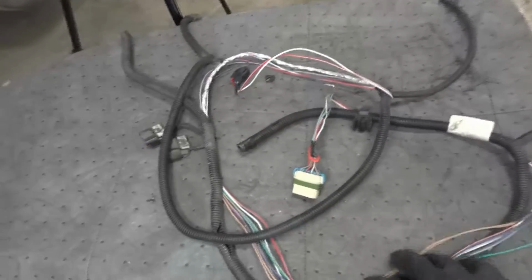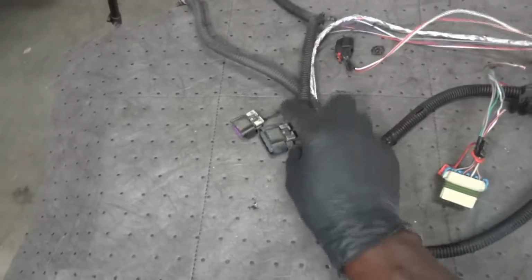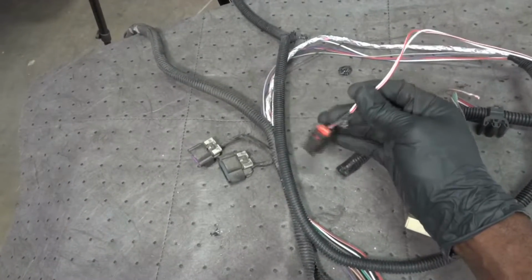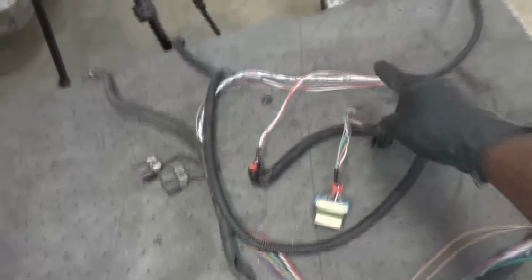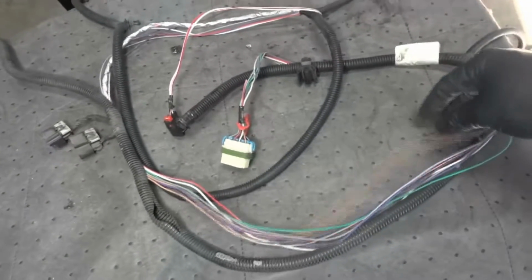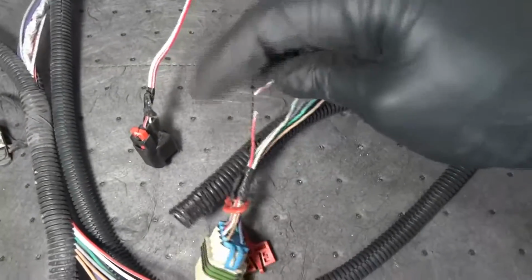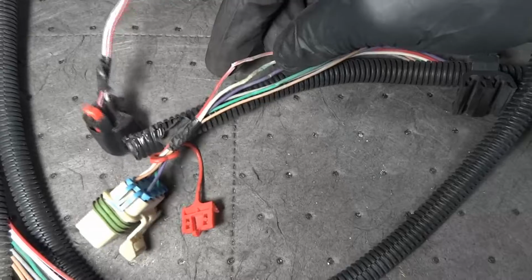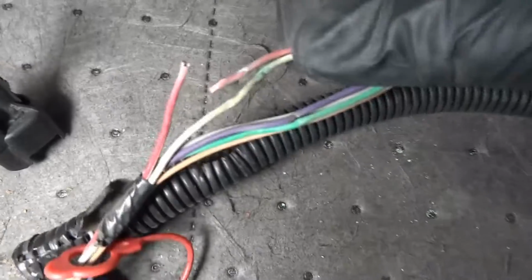Alright guys, so I took the wiring harness out. This is the harness that goes on top of the fuel tank. This over here is the connector for the fuel pump, and right here is the electrical connector of the vent solenoid. So I got the wires out of the wire loom. As I was going down this wire harness, the rest of the wires looked good, but guess what I found? Look over here. So here's our problem. These two wires over here were completely crusty. You see this over here? So this is the problem, guys.